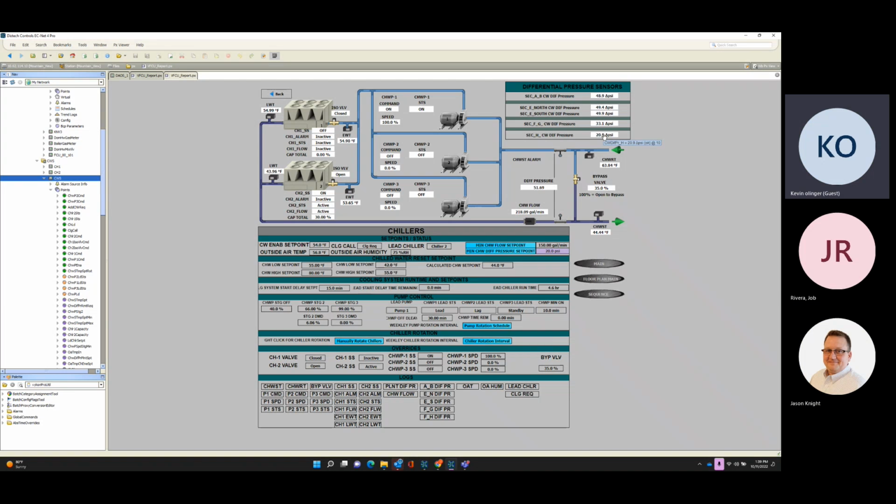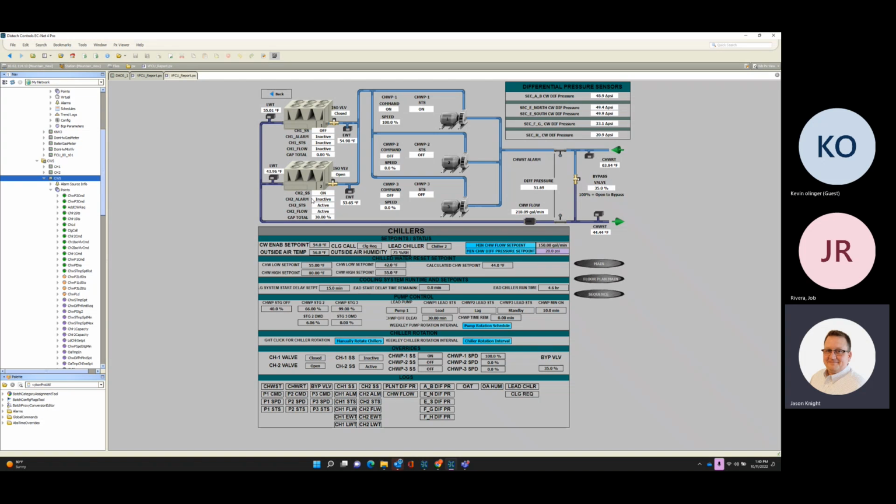And why is there a minimum bypass? The minimum bypass is to maintain enough water through your machines. The other part of the original mechanical sequence called for the minimum flow through the chillers. And I'm like, okay, we should do that with the bypass valve, not the pump control. Then I thought maybe it should be a combination of pump speed and the bypass valve. Well, it turns out we have plenty of pump speed, because just to maintain the minimum pressure, we have to push out to H. But it originally called for a minimum pressure drop across the chillers.